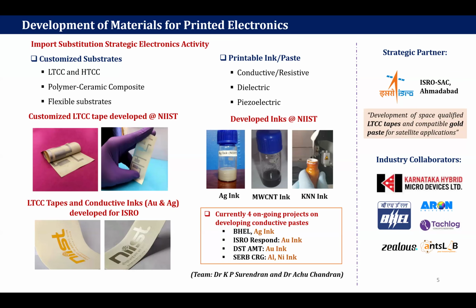Those kinds of MEMS-based devices need precision packaging, and that packaging is provided by LTCC technology. LTCC itself is a technology where you can print various devices on different layers and stack them together, and after firing, that will become a single unit. That is very important for system development, that too reliable systems. The firing happens at around 850 degrees Celsius, and the system is very much reliable.